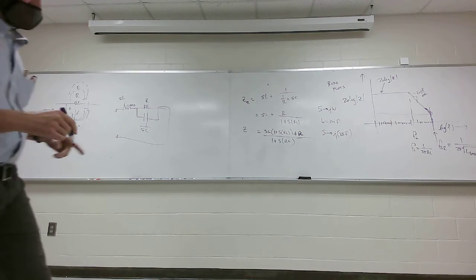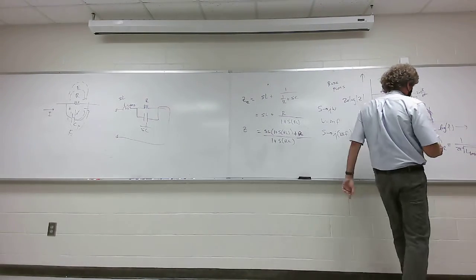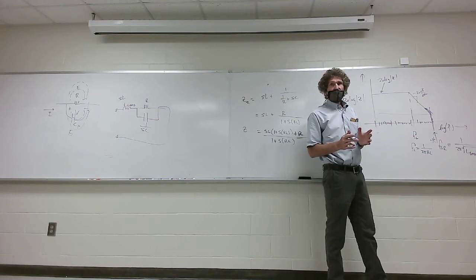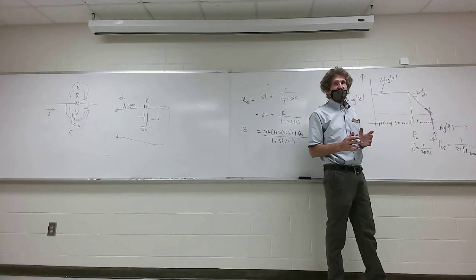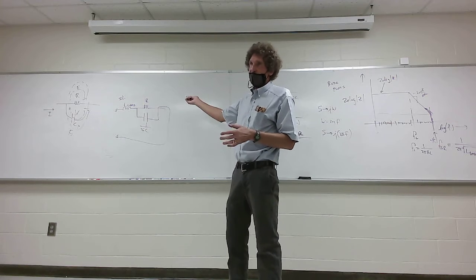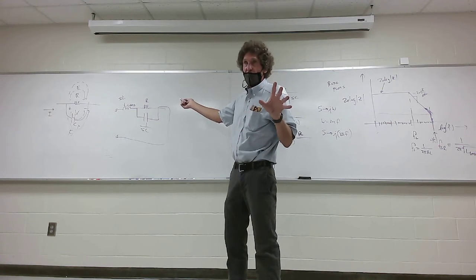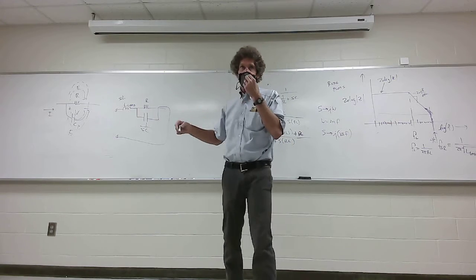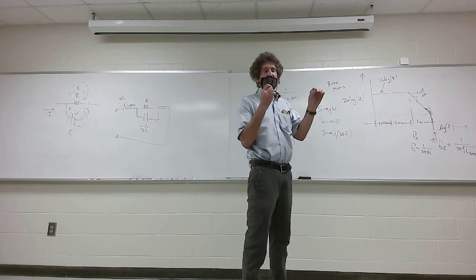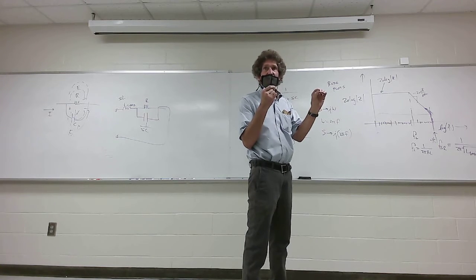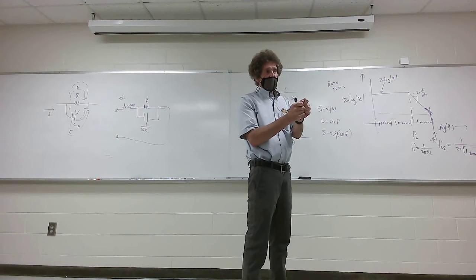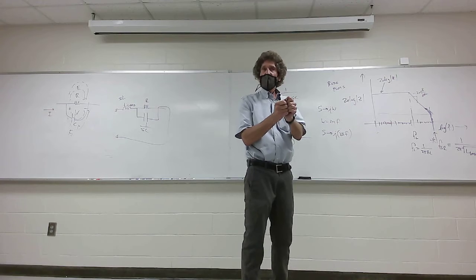Now, that frequency is the one that determines so much. That tells you sort of a limit you don't want to even get close to, whatever the self-resonant frequency is, based on modeling. I'll get to that in a second. You know how to do it for a wire, right? But I've got to talk about resistors, how to do this later. Most of the time, the parasitic capacitance and the lead length will determine the actual self-inductance. Most of the time, they're available from the information you get when you buy the component.